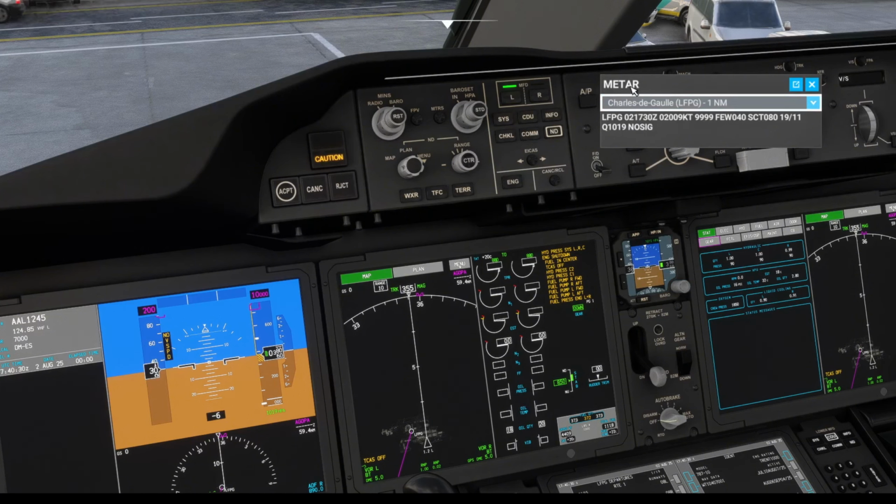So this here is just a METAR, and usually what you need is an ATIS, because the ATIS gives you some special instructions, like which runway you can expect for departure, and sometimes they even tell you what kind of departure you should expect. Sometimes it's labeled as expect 6 Bravo departures, and then you already know you have to look for 6 Bravo and the first waypoint that you filed. Or it could be any other information like birds in vicinity, etc.